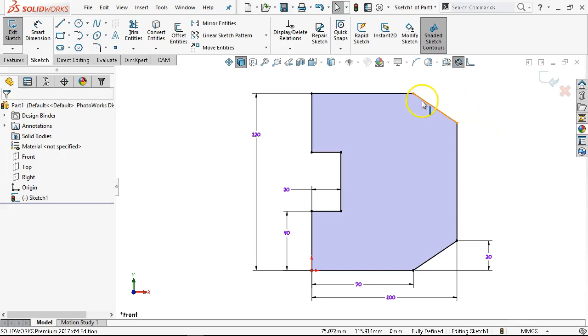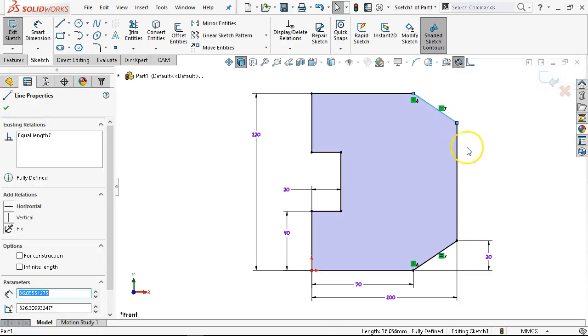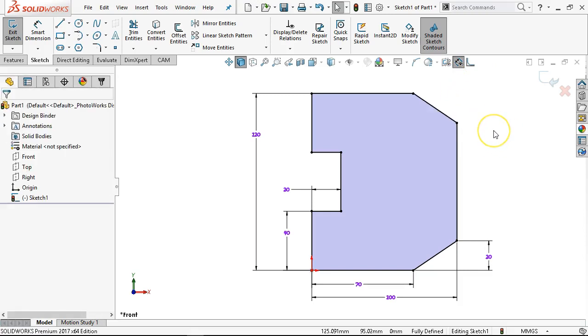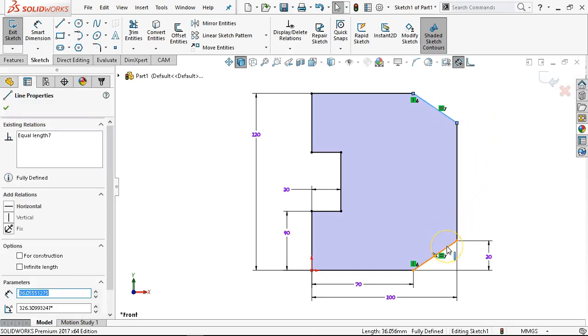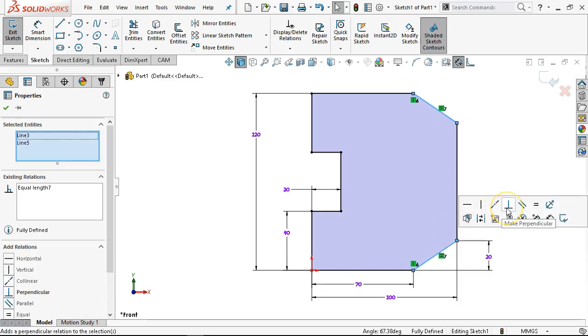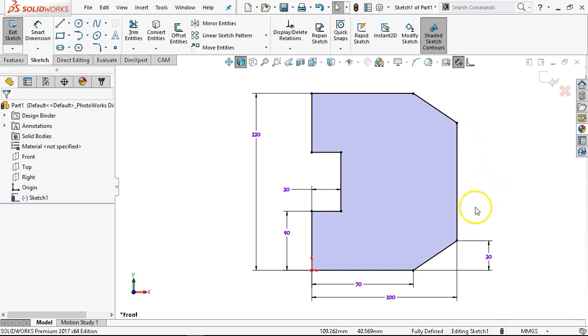All right, so the issue with the equal may be that I get it off a different direction and it would still be equal and satisfy the relations, but not really be the solution that I want. The other thing that would happen if I were to allow it to infer a perpendicular, right? So if I were to see a perpendicular sign in there, then these would automatically go to 90 degrees, and it doesn't really look like they're 90 degrees.